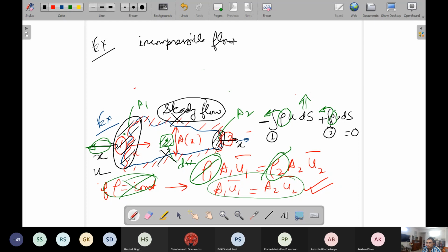So whatever is coming up here is from some considerations related to kinematics in some way or the other. Incompressible flow we most fundamentally derived as a kinematic constraint. The kinematic constraint of incompressible flow is simply the divergence of velocity equal to 0.